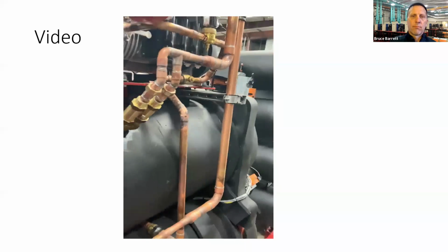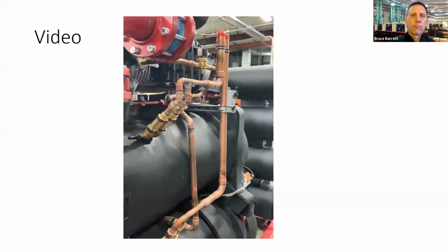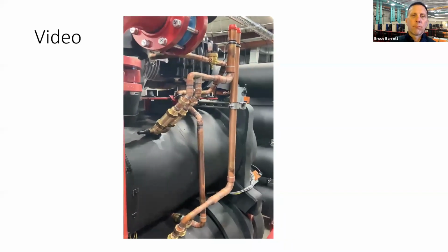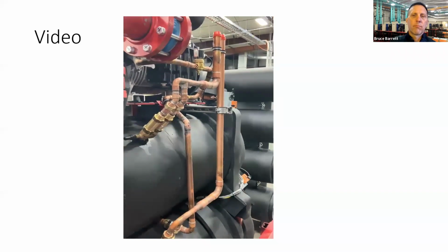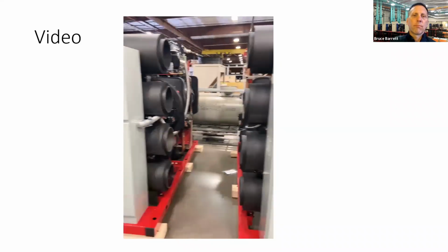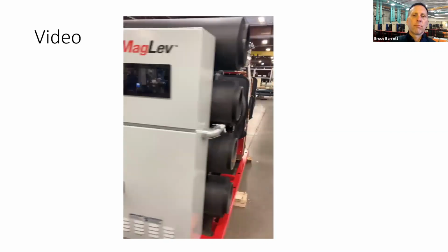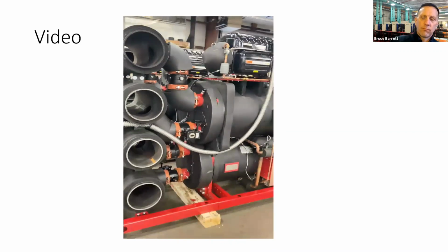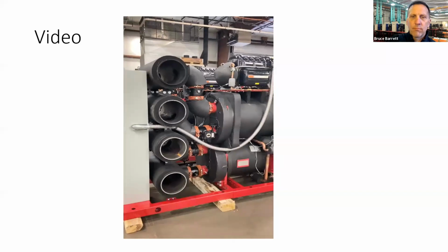Moving on to the inside, the other side of the machine here, a great feature that we just added are the refrigerant vent pipings. Stubbed out above the unit makes it easier for the contractor to install the refrigerant piping discharging out of the building. This particular order has multiple machines, certainly going on the test end pretty soon. Again, this is your 90 to 140 ton modular mag-bearing compact water-cooled chiller.